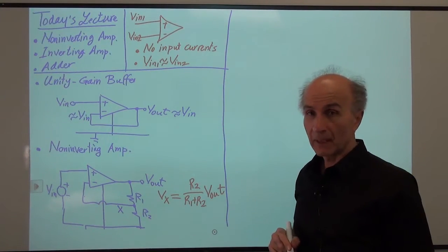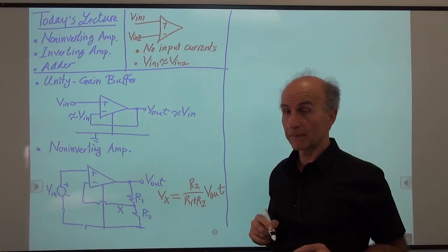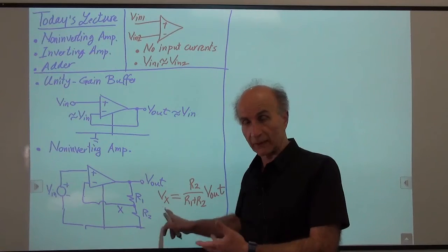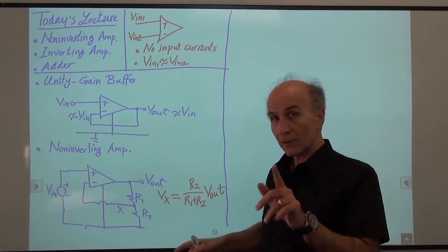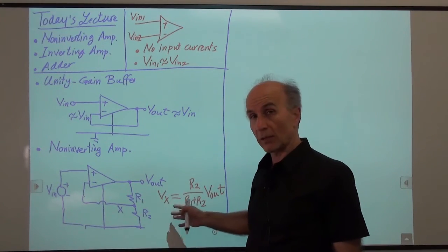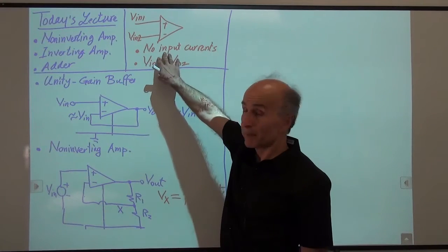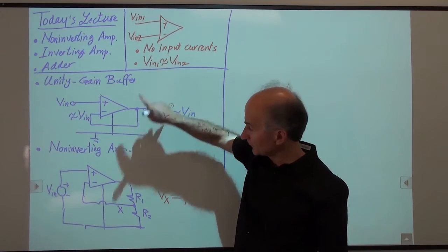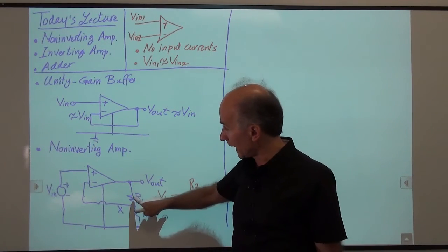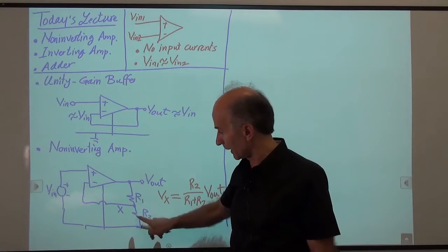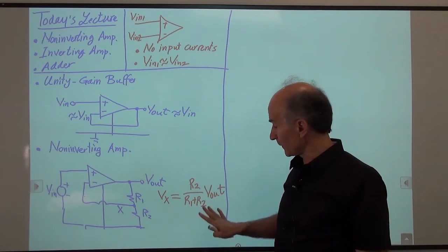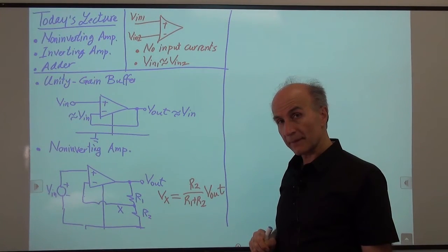Okay, so that's great. Now there's one assumption here that we have to be careful about. This circuit divides this voltage by this value if there is no additional current going this way anywhere, right? If this had some current, the equation would be wrong. And given the assumption that we have made, it's okay. We have assumed that this input of the op amp or this input of the op amp draws no current. So indeed, the voltage divider equation is just this, what we've seen in the past many times. Okay, so we got this voltage for Vx.